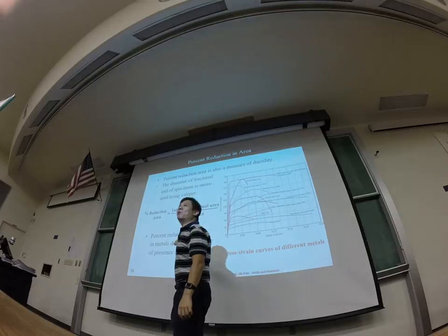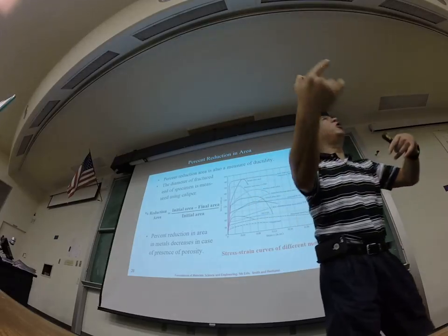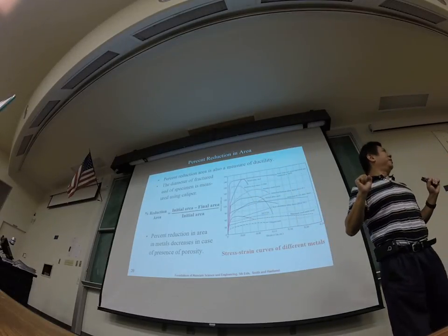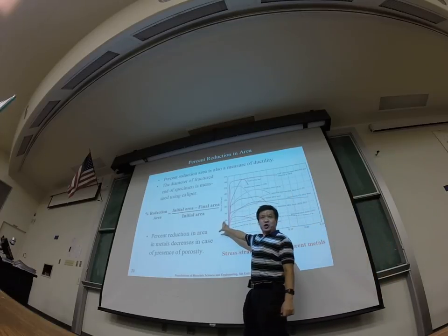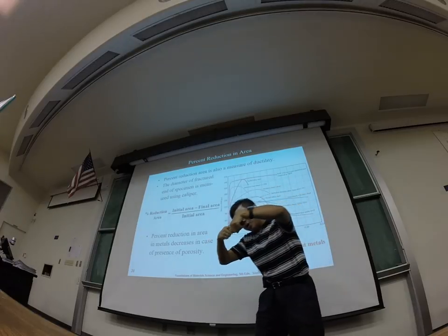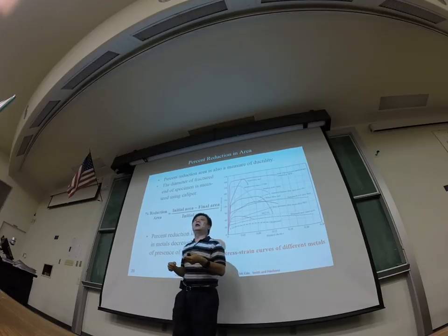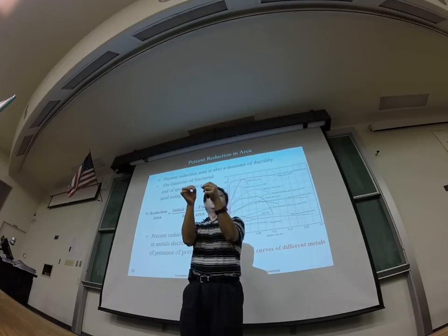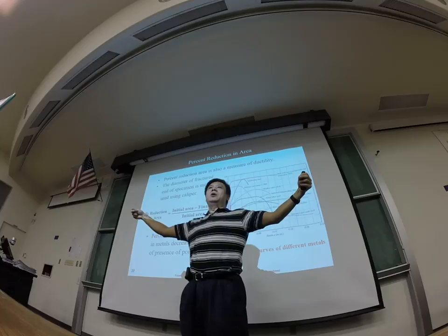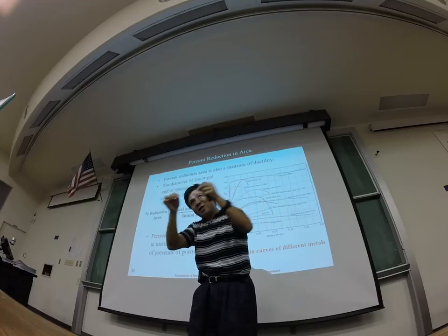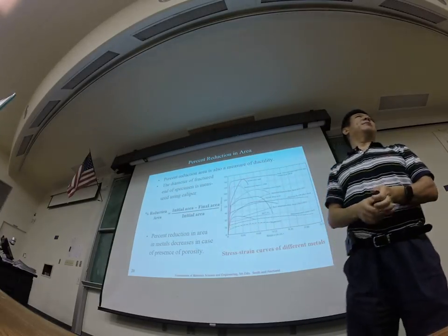So these two parameters are correlated, if we assume the metal does not change volume during the stretching process. So there are two different ways to quantitatively define this ductility. One is measuring the diameter change, which correlates to the percentage reduction in the cross-sectional area. Another is directly measuring the length, how much elongation you get. The more elongation you get, the more ductile the sample. The more reduction in the cross-sectional area means you can elongate the sample more. That means more ductility of the sample, right?